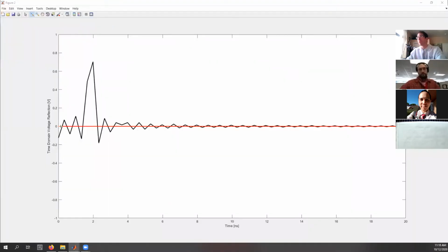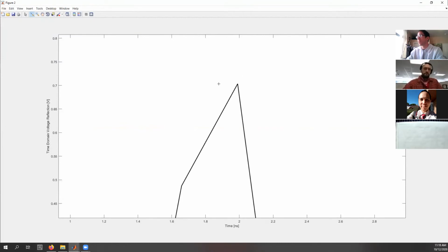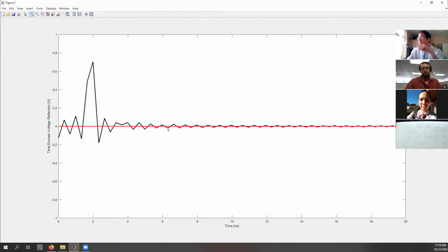You see how it's all garbled because the sampling is awful. And you can see also there's this uncertainty in where the heck is the peak, right? Because we have almost, how much is that? Almost a little over 3/4 of a nanosecond of uncertainty, which translates to multiple centimeters of uncertainty in the length. But you can see it's just a very crudely sampled sinc function.